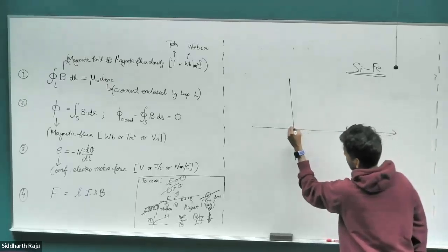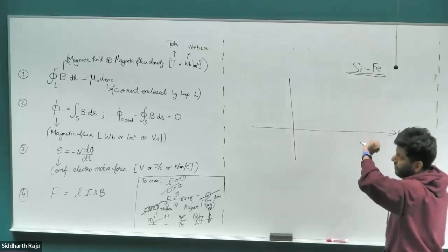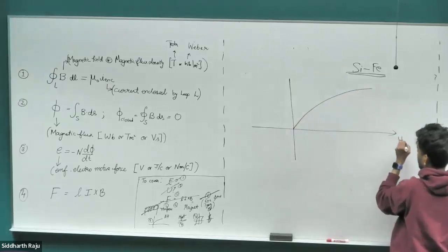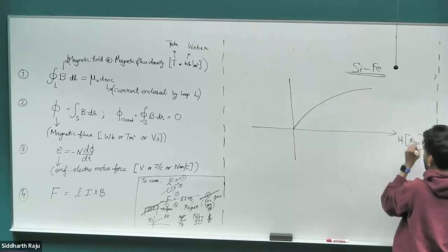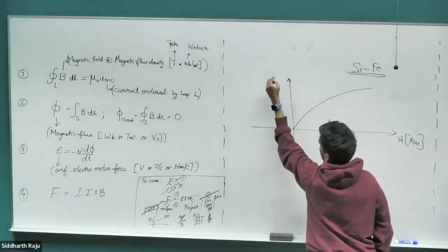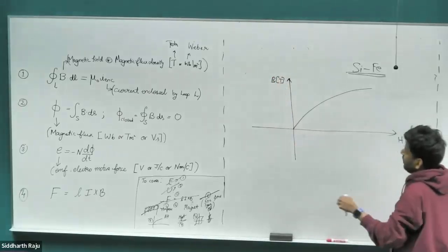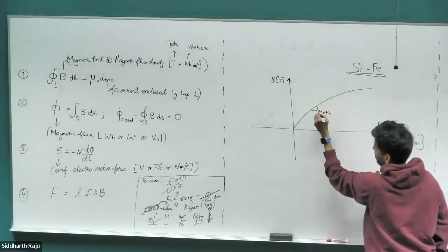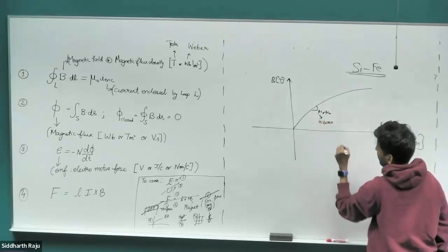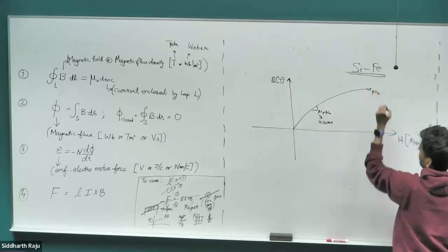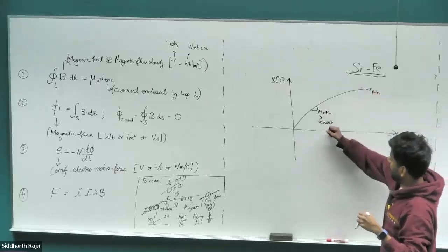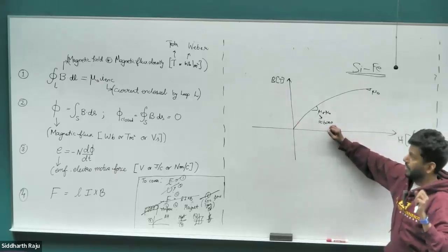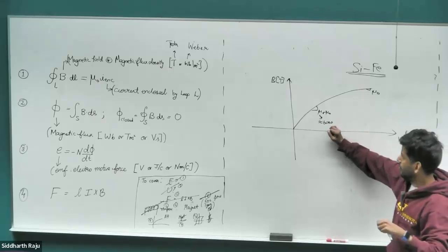But for now, the material used is silicon steel, basically iron with a crystal lattice where some points have silicon injected into them. When this material is first created and has never been exposed to a magnetic field in its life, it gives this characteristic curve that we just saw. So you create a solenoid, insert the core into it, and as you put more and more current, B keeps increasing and then saturates out, with this slope being mu r mu naught. This mu r is typically around 6,000 for materials used in motors. After that, it just becomes like an air gap. That's why I said the magnetic field with an iron core is orders of magnitude, 6,000 times, higher than for a solenoid without iron inside its core.